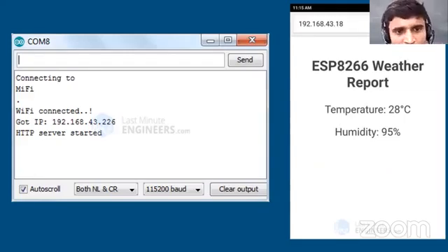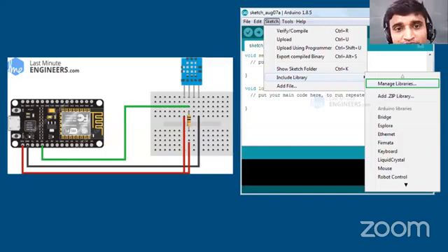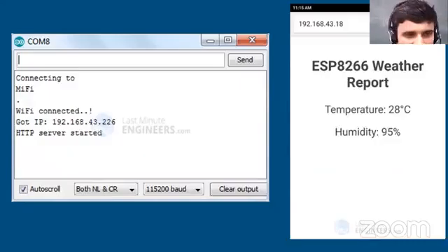This is an example of the components of IoT, where you can use a user interface or gateway. You collect the data, and then after collecting the data, you send it over the network. In NodeMCU, which works on the ESP8266, like in the web server example, you first connect to the NodeMCU server. After connecting, you get an IP address. You can connect to your Wi-Fi hotspot, or to the default hotspot created by NodeMCU.